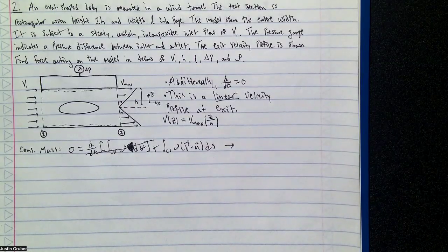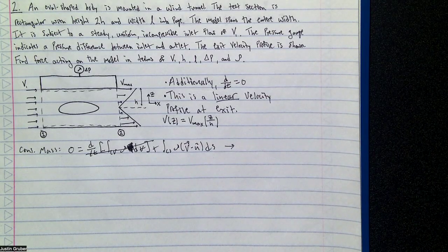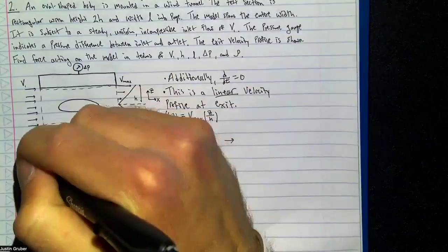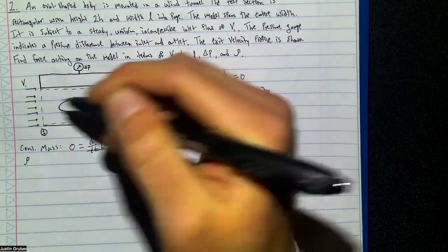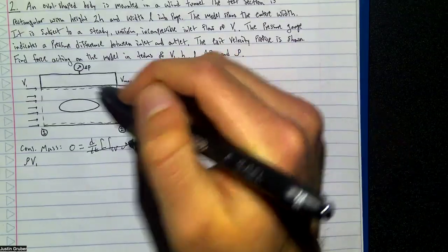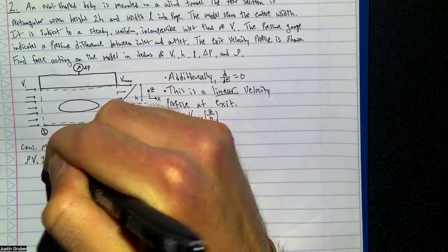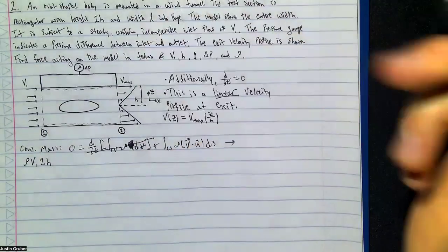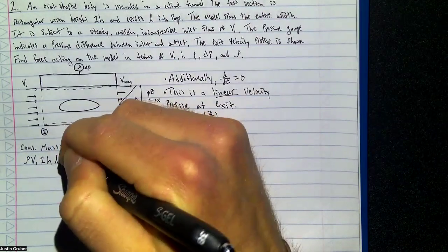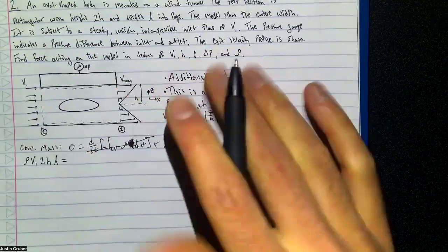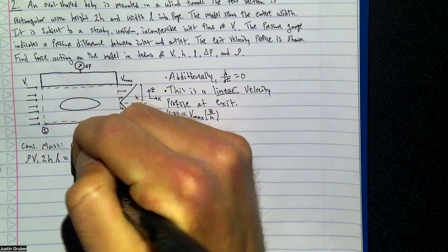M dot in is easy, just what you've always done. Left hand side, technically it's negative, but you flip to the left hand side, becomes positive. So m dot in is just what's our density? It's rho. What's our velocity? It's v1. What's our area? Well, it's 2h because we split this thing symmetrically in half. So it's 2h times the width L into the page. Now equals this integral for the outlet. So what's this integral? You already know.